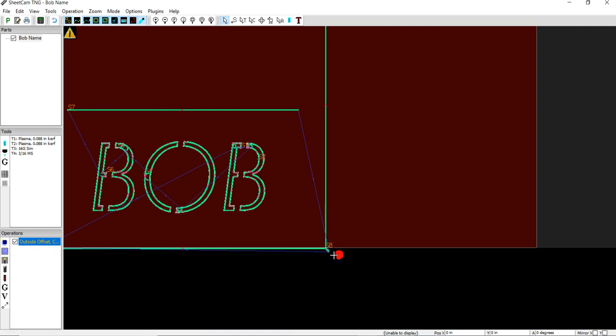That is to say that when the plasma cutter comes in, it's actually going to start on the outside, and you're going to inevitably get a deeper and wider pierce hole when your plasma initially fires. So you want to move the outside of your piece so as not to give it a weird dimple. Come into it and cut around your piece. It's going to cut, come back, and then it's going to arc out. Now similarly, you could say it would do the same thing here, arc in and then arc out, and you'd get some shape that sort of resembles that.